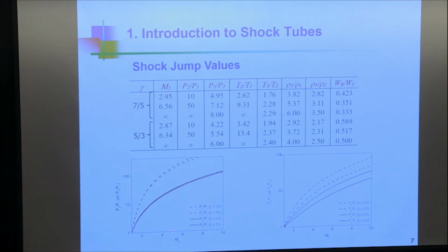So basically the point is, if you have, say, Mach 4, the pressure ratio is 100. No, it's P5. So you augment the pressure by 100 when you produce a Mach 4 shock wave. Now you have to ask what pressure ratio P4 over P1 is needed to do that.